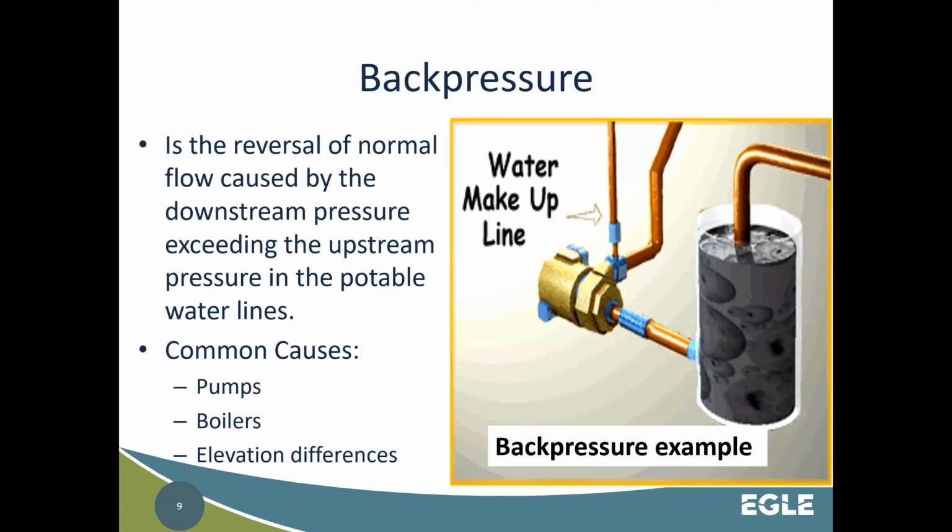Those pumps create a pressure. Boiler creates pressures because it boils the water, and pumps create pressure because they're a pump. Those will create situations of higher pressure within a house, a business, an industry than that of the water system. Most water systems in Michigan run anywhere from 50 to 65 PSI. It's not to say that there isn't higher ones out there, okay? I'm not saying that. There are, but 50 to 70 is like the sweet spot range that most water systems